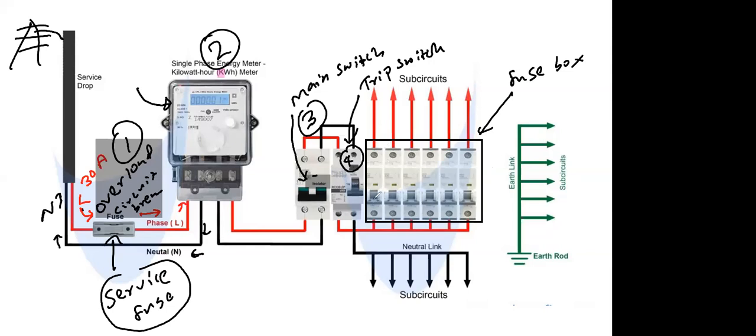Imagine now this is to the kitchen in your house, right? This first fuse. If you off this part, no electricity supply only to the kitchen. So this fuse is the dining area, so all the fans, AC and lamps, all in the dining area. Then if you off this, only that area has no power supply. So if you're doing an electrical repair in the kitchen, no need to off from the main. You can easily off only from this. Otherwise, if you are doing the repair at night, then the entire house is in the dark. So everyone has to stay in the dark. You can overcome that problem if you disconnect the supply from this fuse.